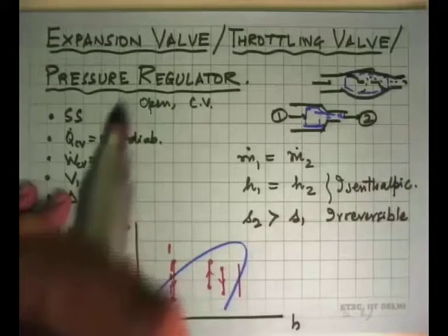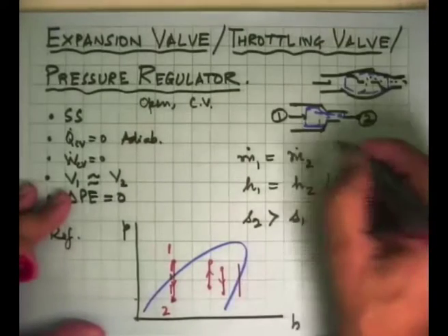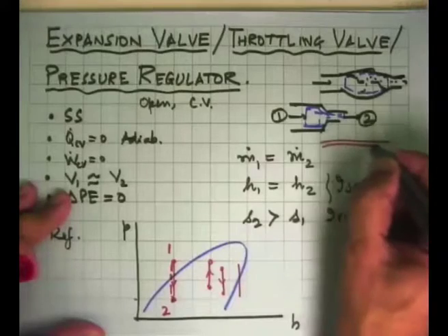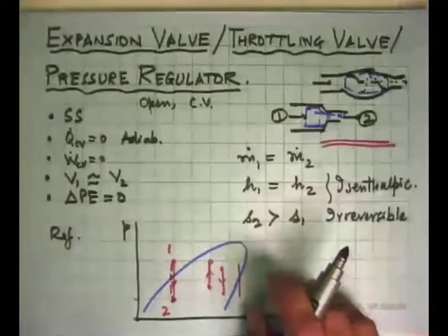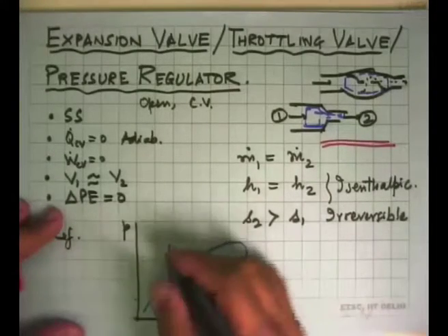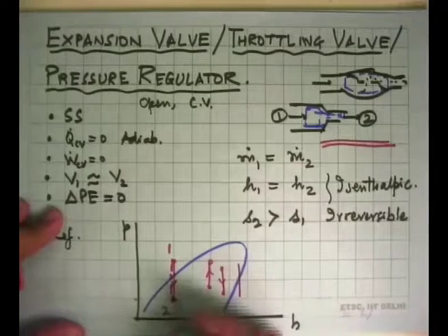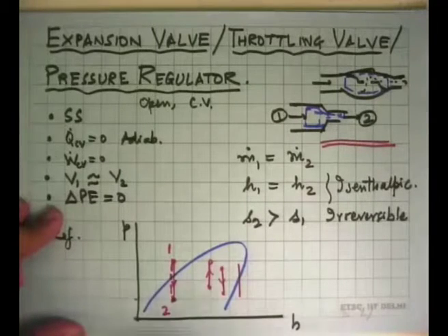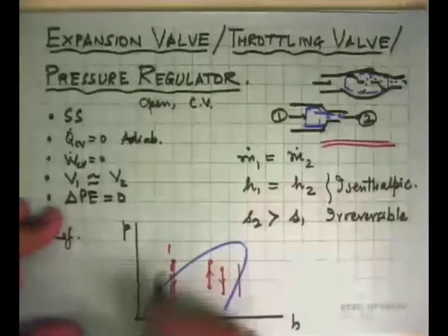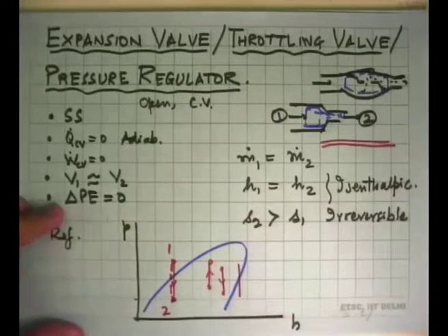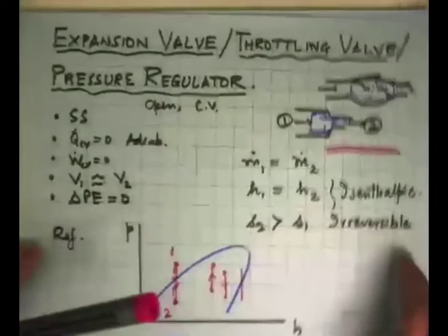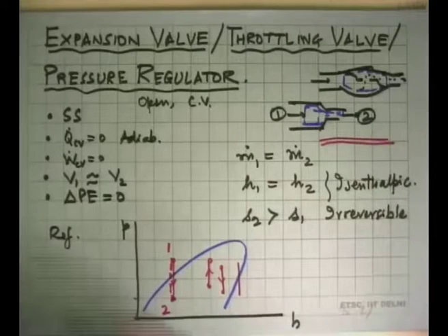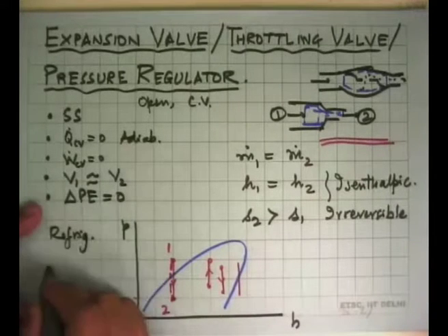And that can be done either through a valve, or we put the refrigerant suddenly through a very narrow tube where there's a very large pressure drop. That's all it does. In the process, a subcooled liquid becomes a saturated state and the wet mixture that you get here. So that's what we use throttling for in all refrigeration systems. The second application that you would all have actually seen is your LPG stove.